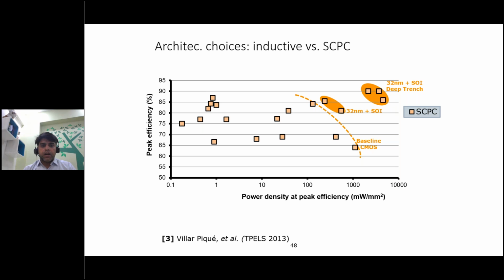One of the challenges I didn't mention earlier was that in the earlier solutions, peak power versus average power was like 8 times, 10 times, 6 times. But lately, because of efficient compact system utilization, you need a very low ratio of peak power versus average power, sometimes 2, 3, or even less than 2.